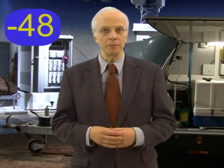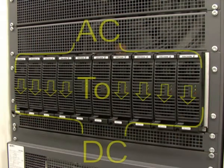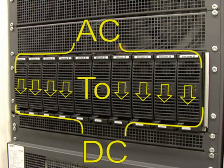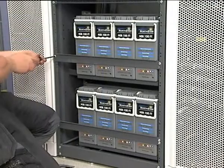The AC that comes from the mains network is then converted to DC. Telecom equipment loads normally operate at a DC supply voltage of -48 or +24 volts. A rectifier converts incoming AC from the mains to DC. The DC from the rectifiers supplies the telecom equipment and charges the batteries.